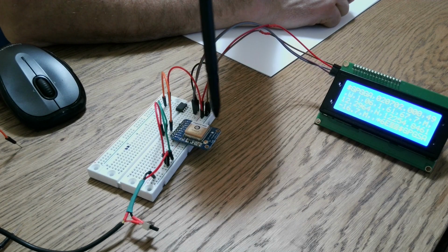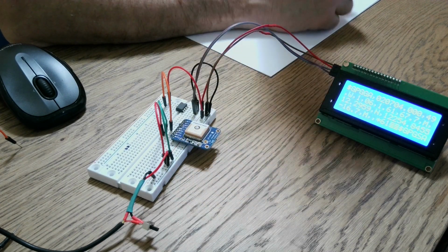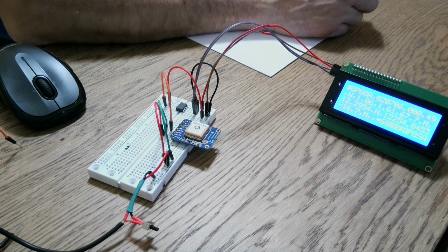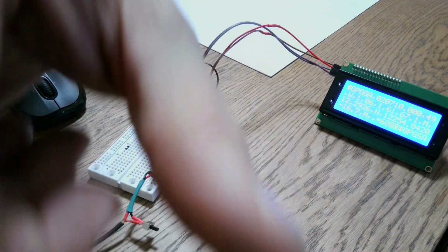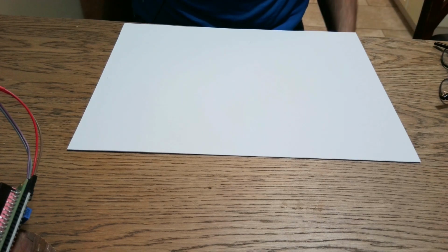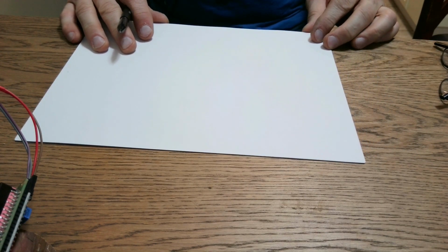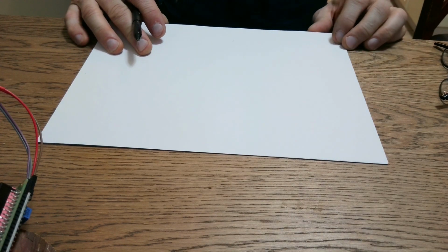And what else can I tell you about this? Yeah, these modules use about 25 milliamps of power. The display uses about 40 milliamps of power. Here, let me just move this over here, so you can see there's obviously a certain amount of power. You can actually turn off your GPS module with an enable bit, and it'd be 1 more I/O port I could use, and I would save power. It'd be down to 6 microamps, I should say, when it's in that state.